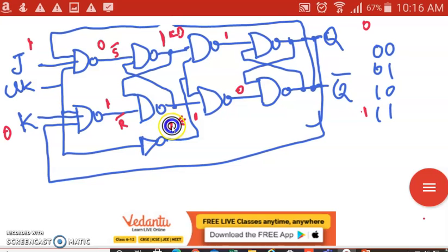So 1 and 0 is the input now for this NAND gate. If one of the inputs for the NAND gate is 0, I'll directly write down this is 1. This is 1. Then for this, it is 1 here and 1 in the negative edge of the clock. So 1, 1, it is 0. So again here I get 0, 1. 0, 1. It is set. So it has been changed to 1 and here it is 0. So this is the output of the JK flip-flop. 1, 0, we get 1, 0 here. So the condition is set.